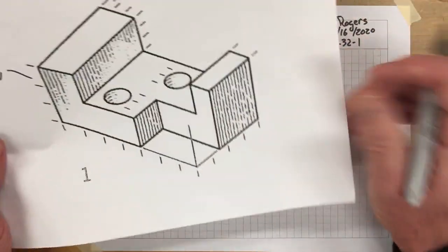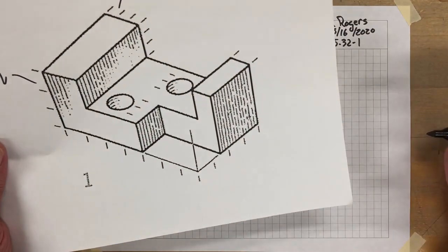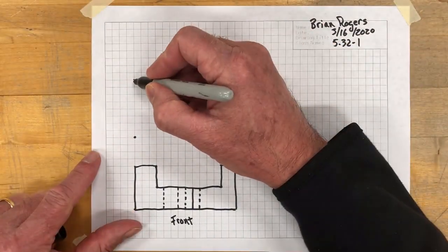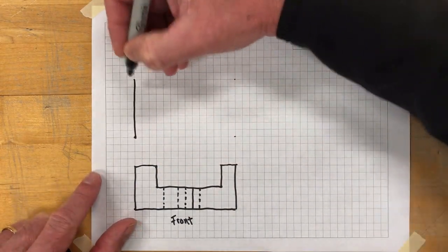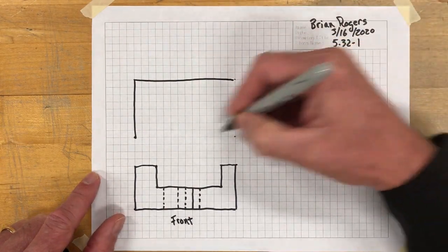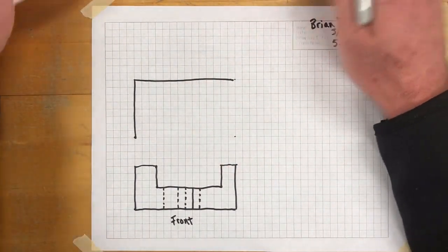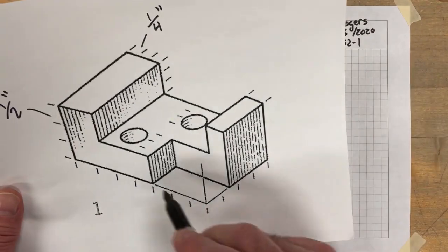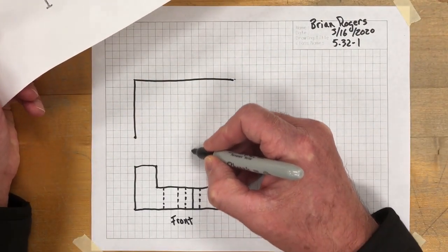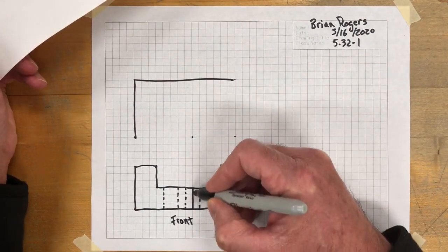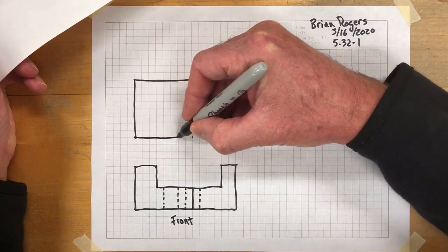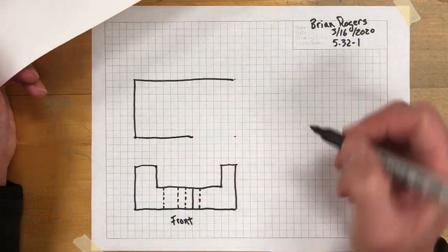Now, overall, this is a rectangle in the top view, the profile is, with the exception of this cutout right here. So I'm going to go ahead and close up the left side and the back. And I'm going to leave the front and the right side open for now. Now, what we have to do is identify where this cutout is. Well, we know some of that information from the front view. I can merely project this along here like this, right along that edge that I've created there, and I could go ahead and connect up that line to that part.